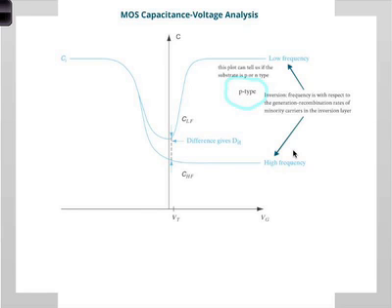They have to be generated. Right? And you also need to account for recombination as they're diffusing. Okay, so if the signal is fast compared to when the generation can happen, then this contribution will be just from the depletion and less from the inversion layer. Okay? You think about that.